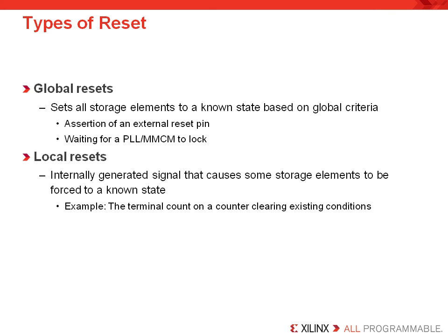But the key thing here is to note a local reset does not reset all the synchronous elements. That's the big difference here. And of course the caveat is a global reset can suck up a lot of wire, a lot of routing resources in the distribution of a global reset. So we try to minimize the number of global resets, but also manage the number of local resets your design has. That's going to be our goal going forward.